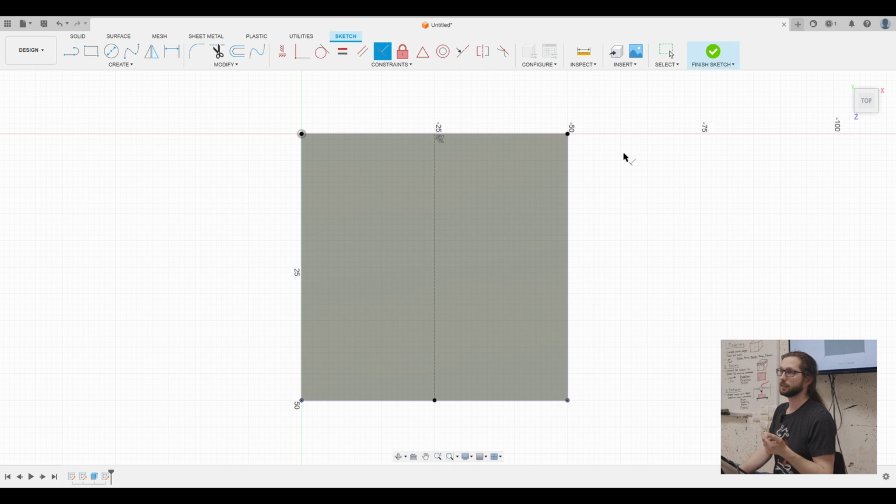So that's after the fact. Yeah, so it is not only not necessary to draw precisely in Fusion, sometimes it is better to draw not precisely to make it very obvious that it is not already constrained, and then constrain it. I will find myself doing that very often. Like if I want a line that is tangent to a circle, I will draw it wildly non-tangent just so I can see it snap into place correctly.